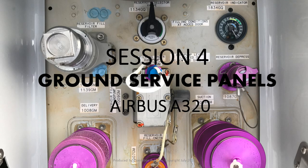Remember, the hand pump is on the yellow system, so you have that located there. More towards the center, you have the yellow reservoir depressurization connection. And at the top left, you have the ground test pressure connection, so you have that to plug in. Again, this is just giving the orientation of the different parts on the ground service panel.